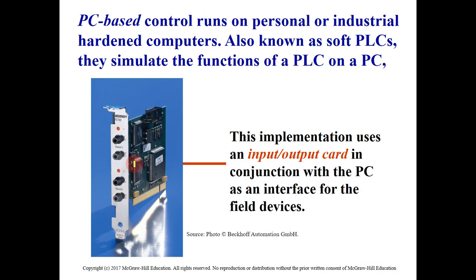The third type of addressing, we said it is PC based, and we said it's usually used with the software or with the PC with an interface. You can see here, this one is a card or interface which is integrated or installed in the PC, or in the personal computer, to simulate the real PLC system. So in this case, when you install such a card in your PC and you are going to run some software for PLC, in that software you need to use the PC based addressing just to simulate the real PLC system.